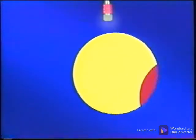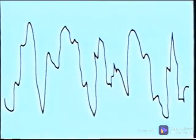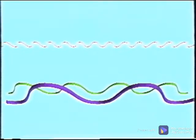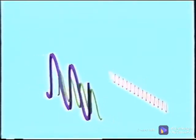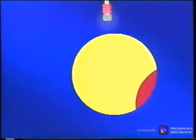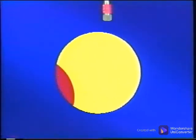When a vibration sensor is mounted on an unbalanced machine, the unbalance will bump the sensor once during each revolution of the shaft. Recall from another program, Introduction to Vibration Analysis, how a machine's vibration generates particular waveform patterns, and how the waveform is transformed into a spectrum where each peak in the spectrum represents actual movement in the machine. Unbalance generates a bump on the sensor once each revolution of the shaft, so we expect a peak in the spectrum at a frequency equal to shaft speed.